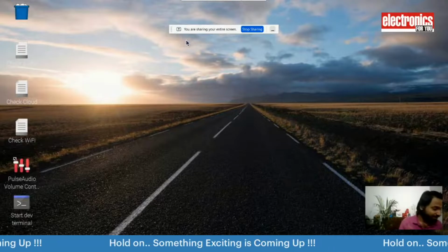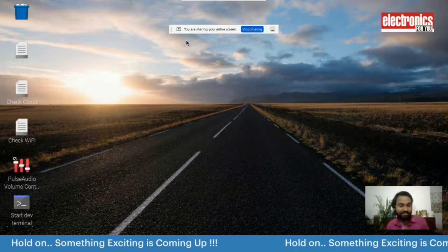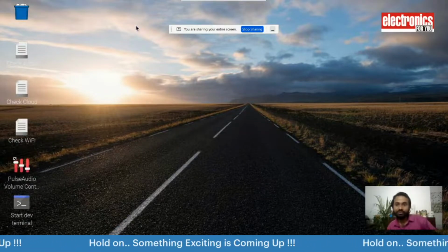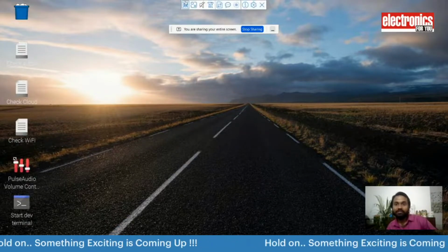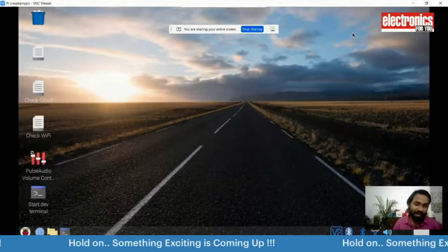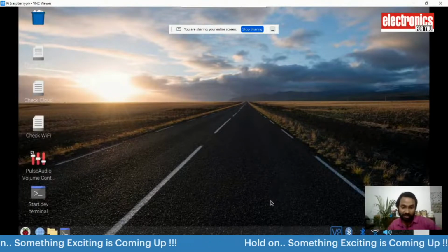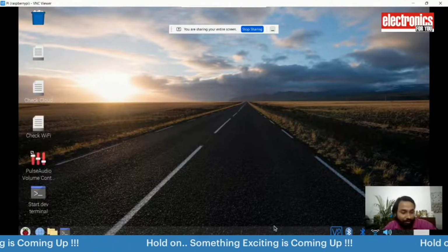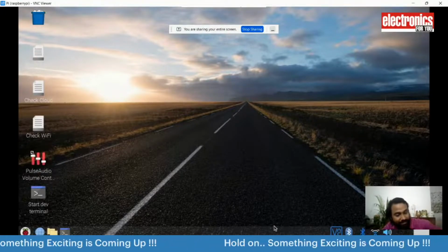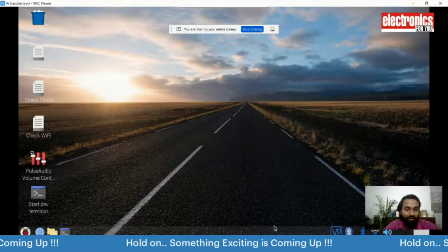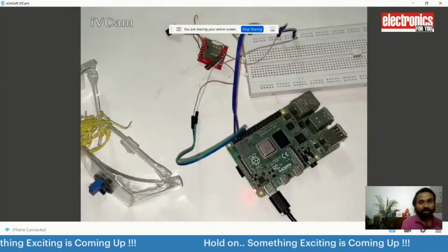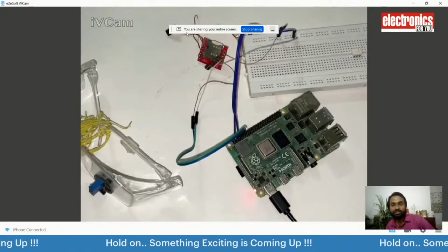So let's first understand the process of making this. Here we are using the SIM800L module for making phone calls, embedding the phone inside our eyeglass, our smart Google Glass. For that we need a library so that we can interface this SIM800L module. This SIM800L module will work on USART, or you can say serial communication.